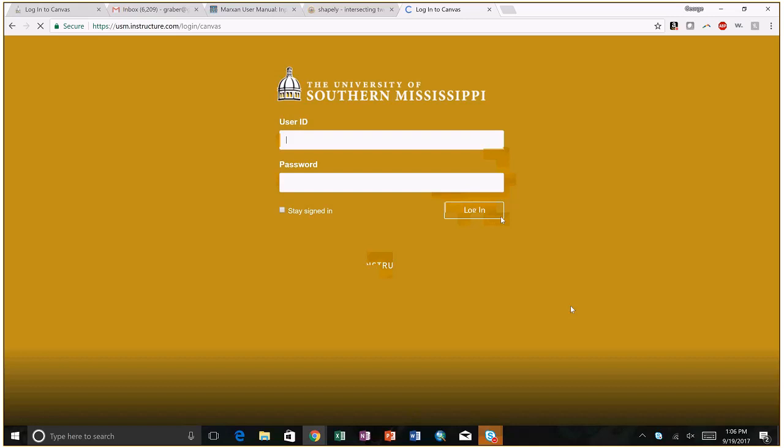What it does is it averages the corrective factor out. Let's say you're right here, it'll average out the error that it sees in all three of these, and it will be able to correct you somewhat. People have shown that it does work. It doesn't get you as precise as a true real-time or post-processed differential correction, because the stations are further away. The error is more unknown.